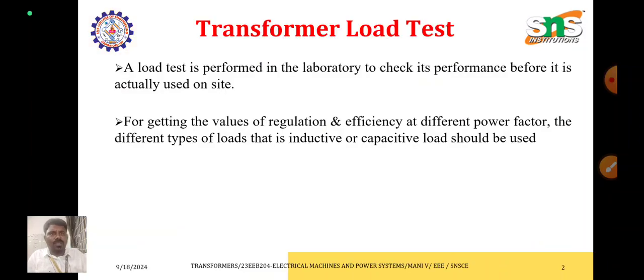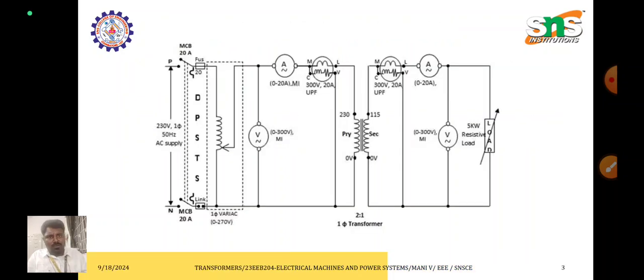Today we are going to see about the load test and the regulation of a single phase transformer. The transformer load test is performed in the laboratory to determine the efficiency and regulation of the transformer before it is actually used in particular applications. For getting the value of regulation and efficiency at different power factors, different types of loads, that is inductive or capacitive loads, should be used.